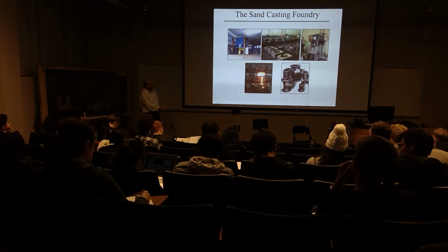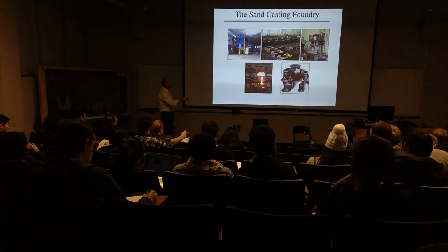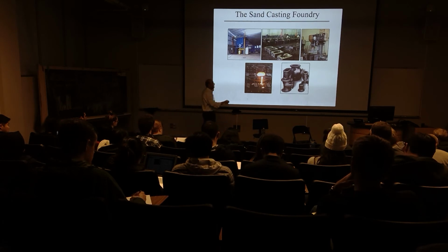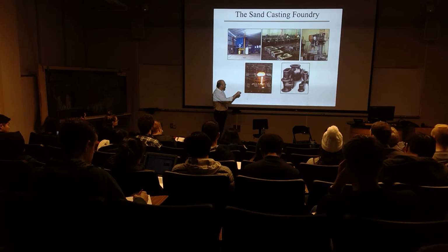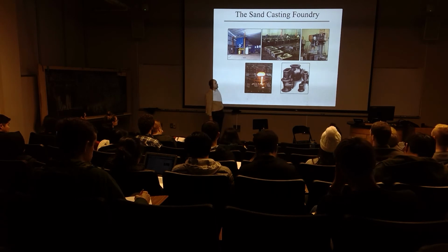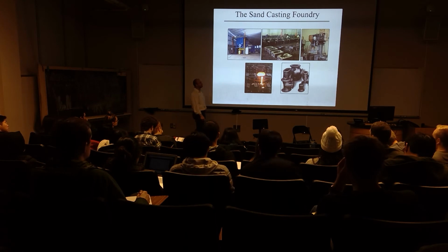So in expendable mold processes, we have to be able to use a binder for the sand, make the mold, densify the mold characteristics, pour the metal, and then shake out the part. And all of these processes, one after another, can actually contribute to the introduction of defects that might be present. We'll talk about the major features that you can get.